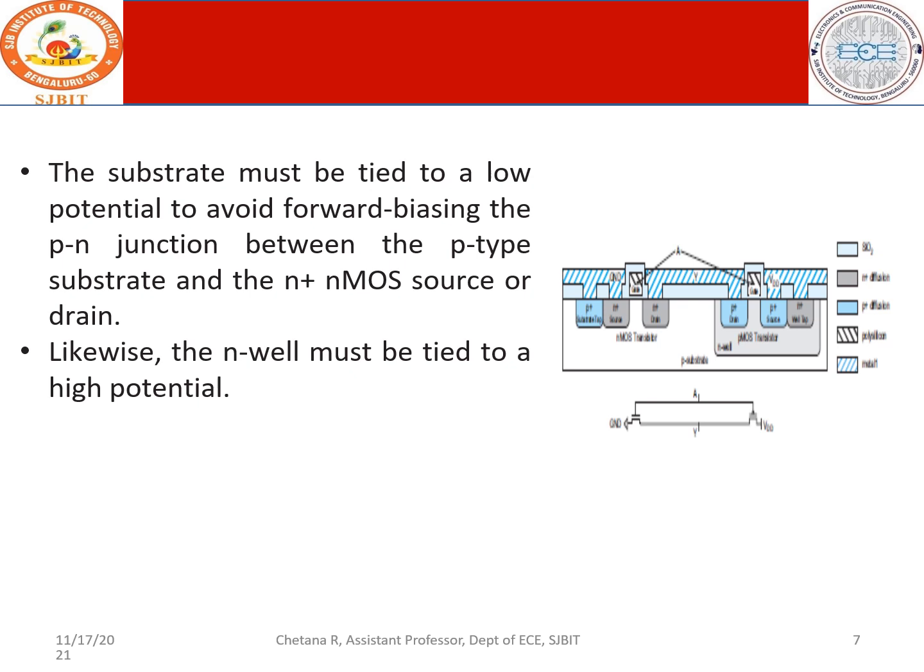The leakage current in turn abruptly varies the threshold voltage. Variation of threshold voltage will have a drastic effect on so many parameters, and number one, the drain current is going to change. Therefore, see to it that the junctions here are not going to conduct. How is it possible? The only possibility is to connect the substrate to ground.